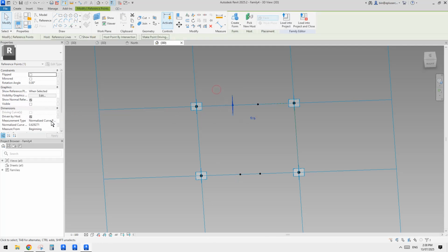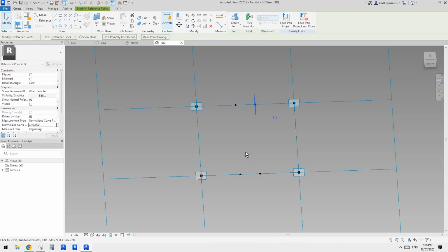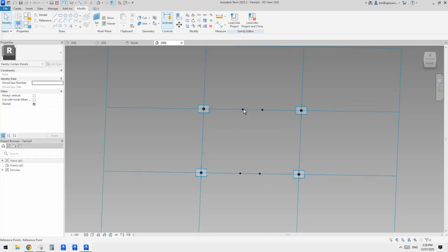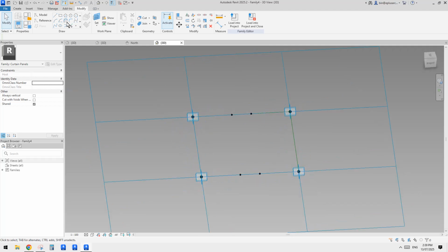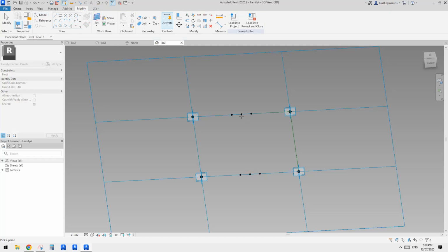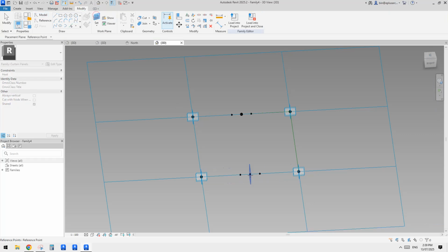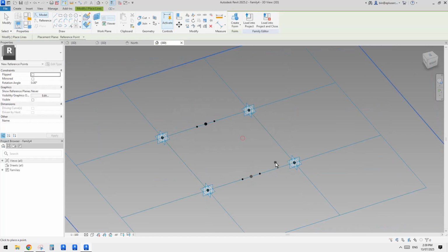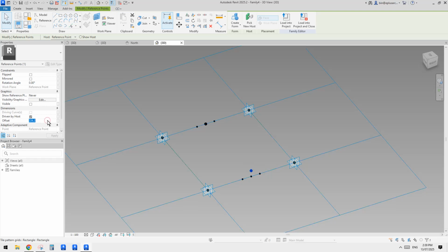I'll just do this roughly. So this is measured from the other side. I'll just use 0.6, so which means this one will be 0.4. I'll just use this one 0.6, and then how do we have a little ridge here? Yeah, I'm not sure. Just place a point in the middle and use draw work plane and place onto the horizontal work plane of the point, and then I'll just use offset. I'll just do another one here and just offset it. Okay, so I guess 50.